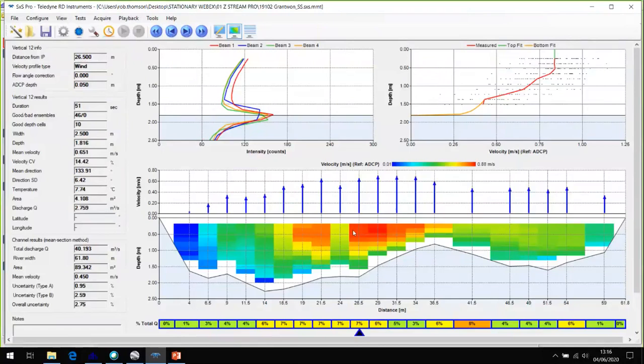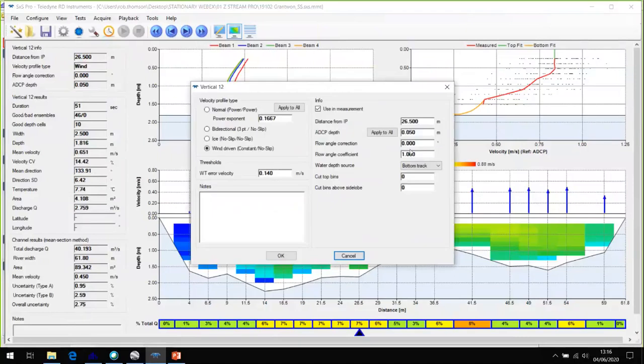But they allow the sensor to rotate freely around in the river and always then reference the true flow, reference the azimuth. So in this case with the Stream Pro, if this sensor is rotating around, it's not compensating for the right direction of flow because there's no compass. So if it was skewed, we started to mention that in the previous one, but if this actually was that skewed, it's not going to know, and you'd have to put a flow angle correction in here to account for that, as you would with Sontek sensors if your compass was turned off and your float was skewed in the river.